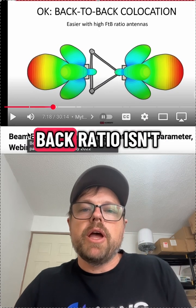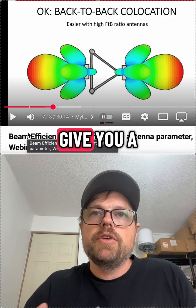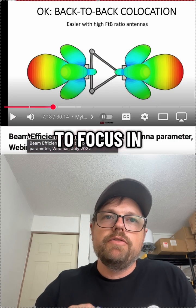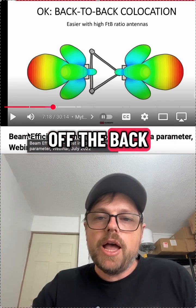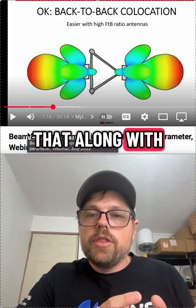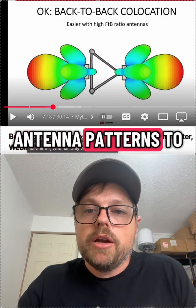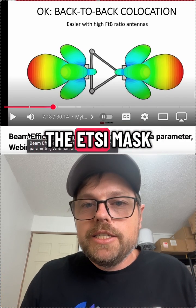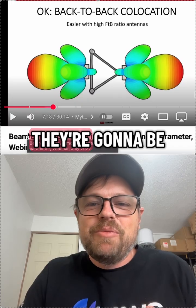So again, the front to back ratio isn't going to give you a complete picture about an antenna, but it's going to give you a good idea about the antenna's ability to focus in a specific direction versus the amount of energy leaking out the back. And that ratio, you can then use along with other things like gain, along with looking at the detailed antenna patterns, to get an idea about the overall picture. You can use the ETSI mask, which they mentioned earlier in this presentation. They're going to be dismissing that as well.